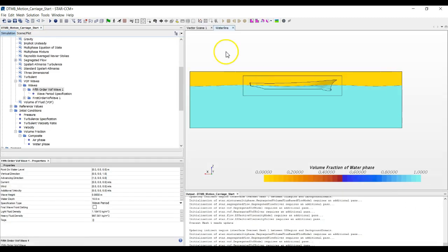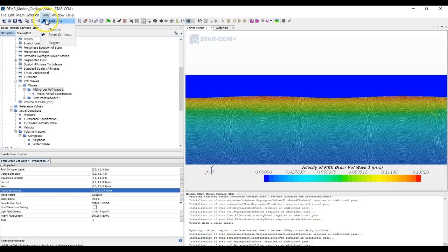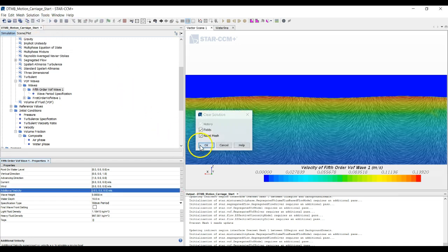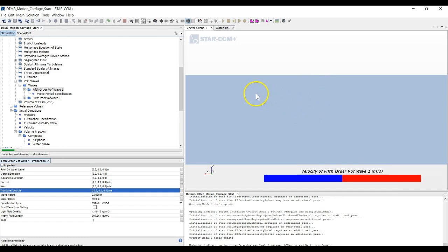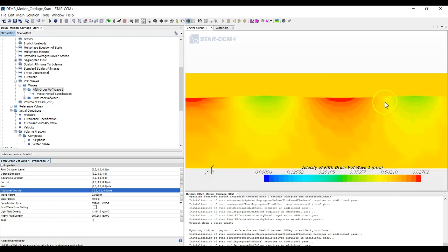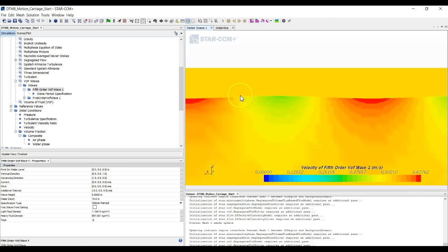The second is that the additional velocity for a fifth order wave purely superposes this additional velocity on top of the computed theoretical wave velocity. It is a simplistic model and useful for small ship velocities when compared to the wave velocity itself. It is still valid at higher ship velocities, however the higher the ship velocity when compared to the wave velocity, the more error is likely to be present due to the superposition.